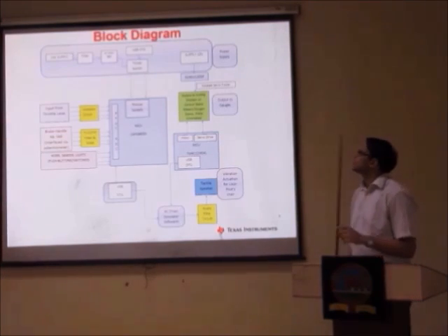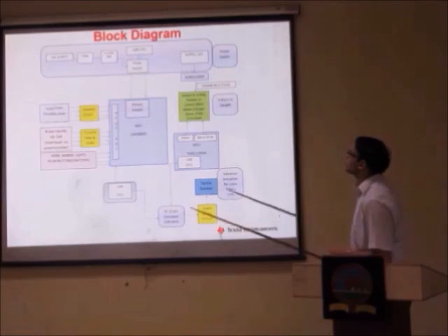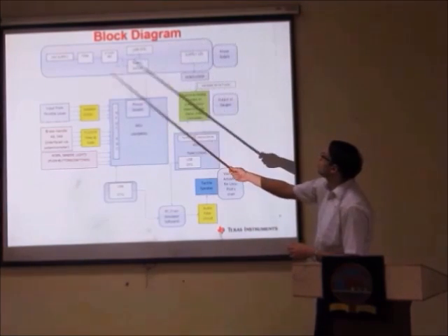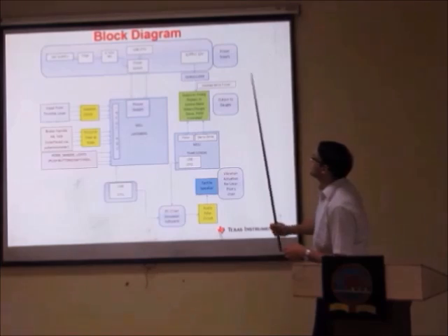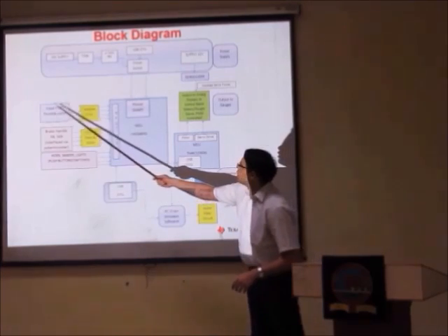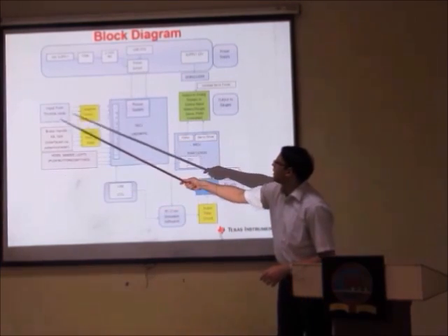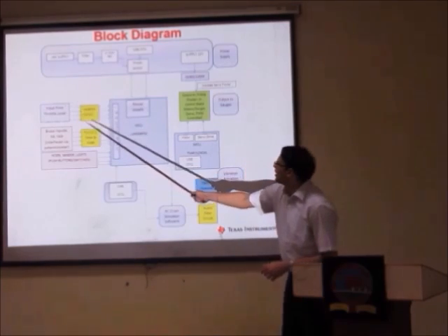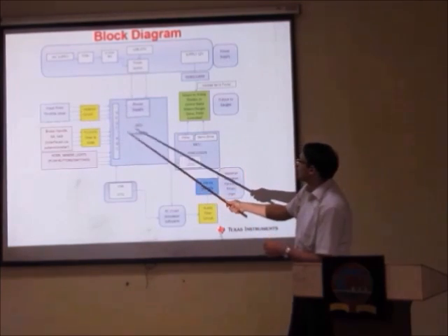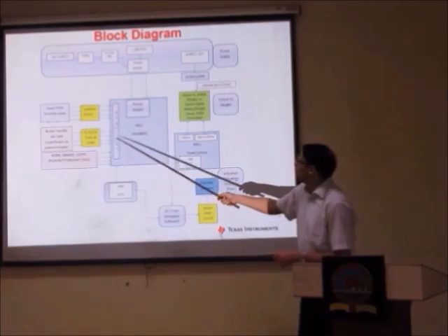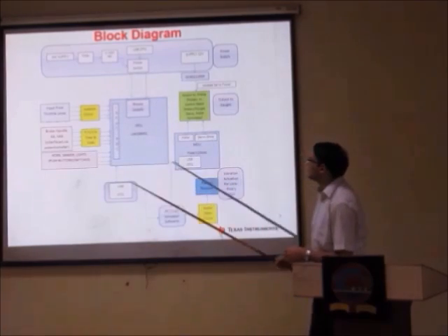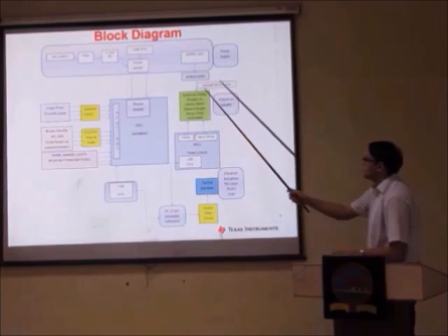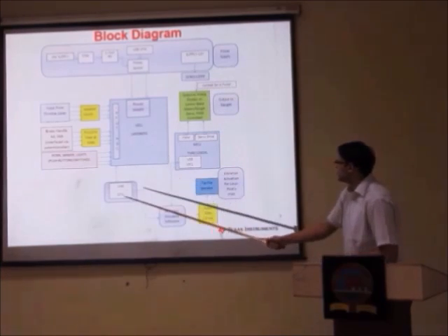Here is the overall system level block diagram of our project. Here you can see we have used a 24 volt or 12 volt power supply for driving the circuit. The different inputs from the control stand are indicated over here. We take the inputs from the throttle lever through an isolation circuit before feeding them to the microcontroller. We are using a TLP2374 based circuit for filtering and scaling the analog inputs from the potentiometer. All of this data is fed to the PC using USB.